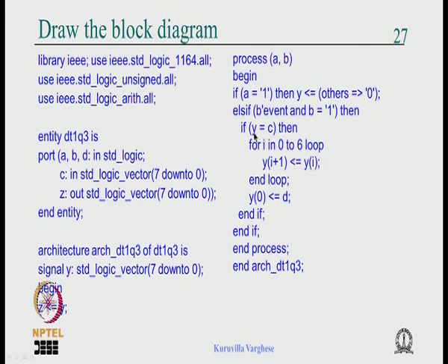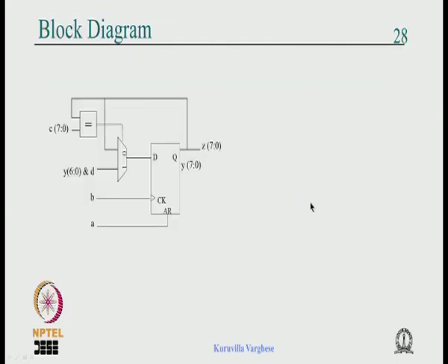So Y equal to C goes to a 2-to-1 mux, and the Y equal to C output is the select line of that mux. At one input is the shifted value, and at the other the same value goes back. That is it, and that is what is shown here. We have an 8-bit register, so these are thick lines.